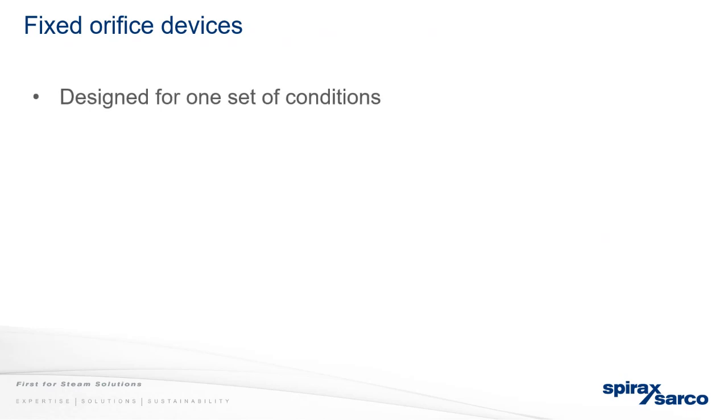They're designed for one set of conditions, so they work very well where you have a constant load. They're unable to handle load fluctuations, as we said, because the size of that orifice is designed for specific conditions. So if that changes in any kind of way, they don't handle it very well.